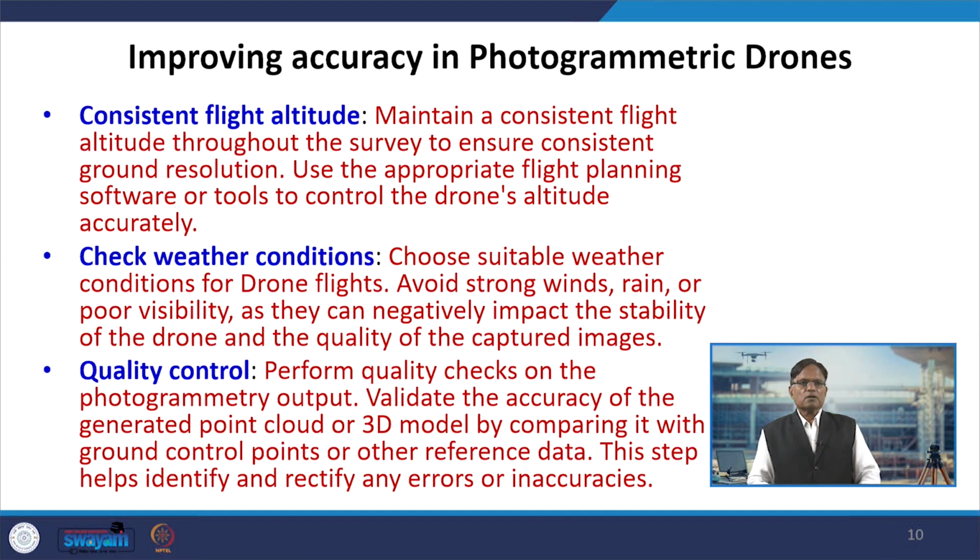Then, continuing the slide, consistent flight altitude is important. We have to maintain a very consistent flight altitude throughout the survey to ensure we have consistent ground resolution and scale of the mapping. So, we use appropriate flight planning software or tools so that the drone maintains the altitude accurately and with stability.